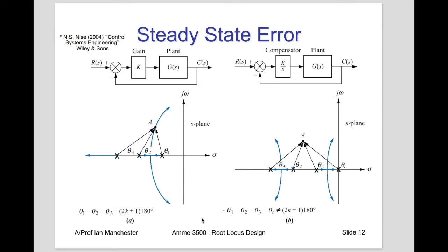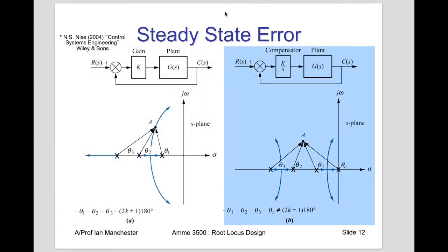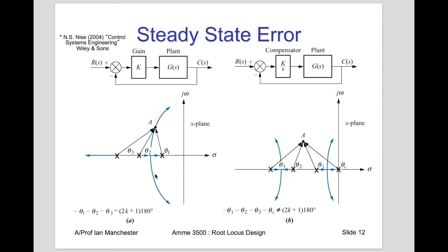They're going to keep going up at plus or minus 60 degrees. So let's say we're able to choose a particular gain that placed the poles at some value A, and of course it's going to be minus A as well, the complex conjugate of A.